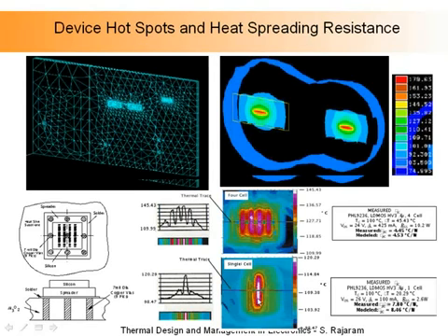So these are all factors that we take into account when we design products, looking at how we can minimize temperature. We distribute the heat, we minimize the resistance. These are all things that we look at from both a measurement and modeling perspective. But I just want to give you an idea of real-world design parameters that we deal with. Okay, and this is a real design where the devices are each dissipating about 80 watts. And basically what the spreading resistance does is lead to these device hotspots. And these device hotspots are what we are trying to cool and keep under control.